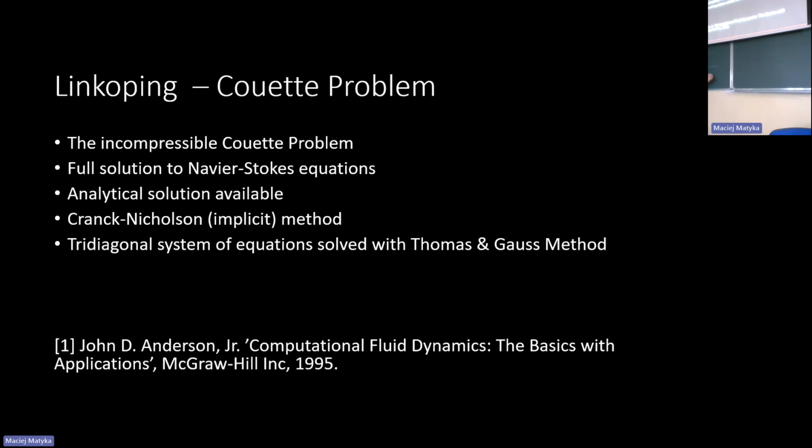This will be everywhere later because it's very standard, common, and people use it. It says that the velocity is equal to 0. And not the velocity as a whole, because the velocity is a vector, but the component which is parallel to the wall. So the parallel velocity component is equal to 0. That means the fluid has 0 velocity exactly at the wall, which is basically pretty obvious.